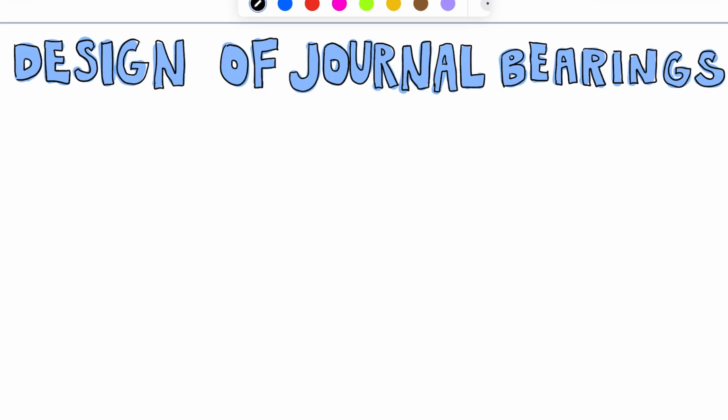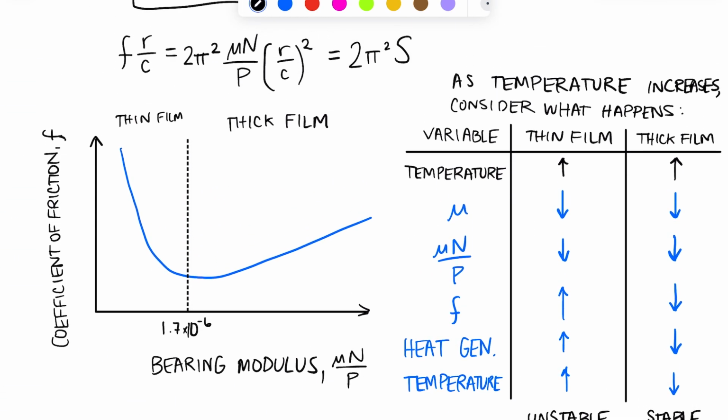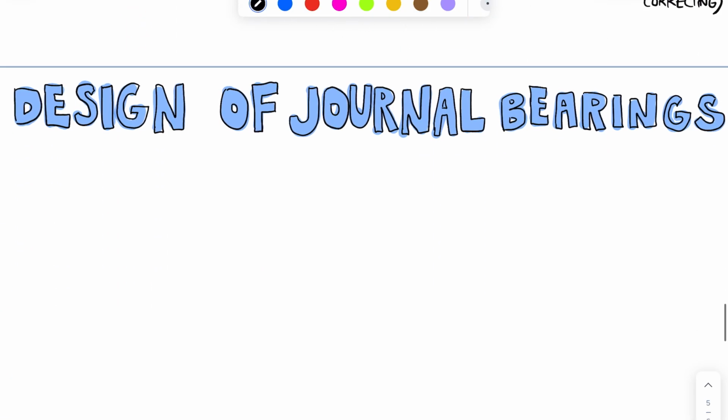So in our last video, we developed some relationships between variables that we defined for journal bearings, things like the bearing modulus, which has to do with the dynamic viscosity, the speed that the journal is rotating, and the pressure of the lubricant in the bearing. And we developed these parameters through Petrov's equation. So if you haven't seen that video and you're curious about where these things are coming from, I encourage you to check that out.